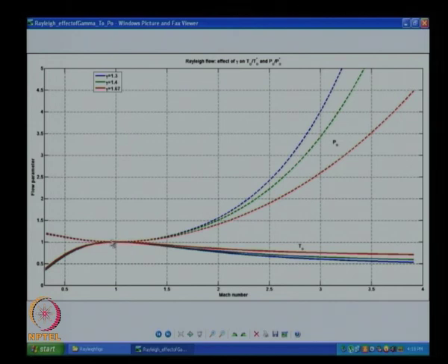By the way, if I am cooling, it can go the other direction. Okay, always remember that we are thinking about heating only as of now. If I cool, everything goes the opposite direction. I can remove a lot of heat from m equal to 1 flow if I go subsonic path, if I am cooling. Okay. Anyways, so now we will just think about P naught curve.